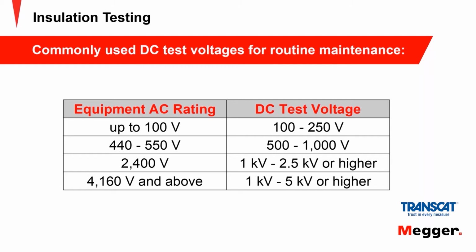But note that the standards agencies have noted that for equipment that's running well up into medium voltage, you can't be expected to have an expensive, heavy insulation tester that puts out 50 kV or something like that. So typically, if you get up around 15 kV, you're good to go on just about any type of equipment to test the insulation values.